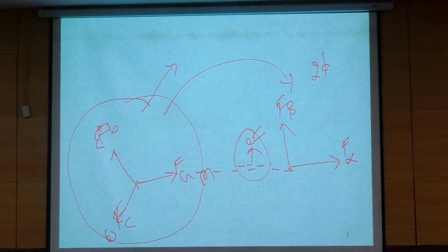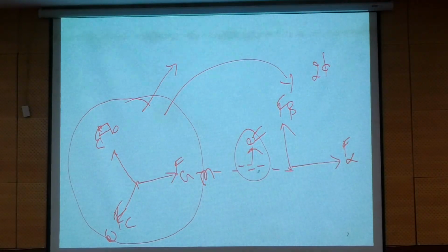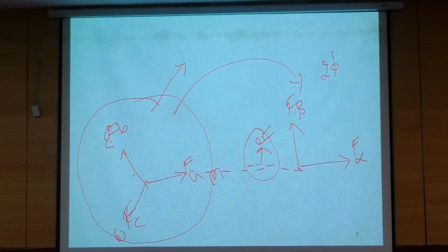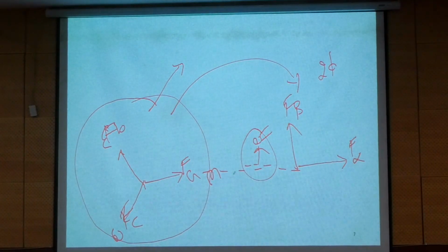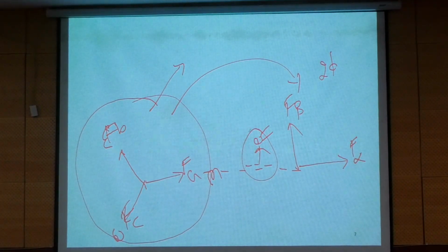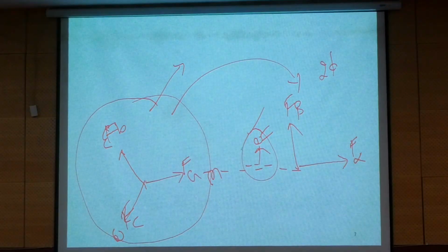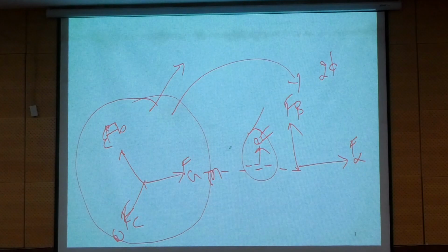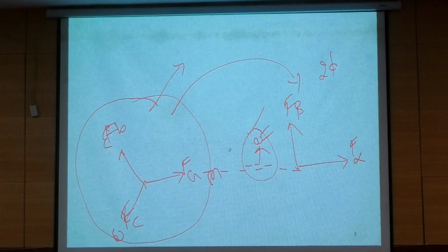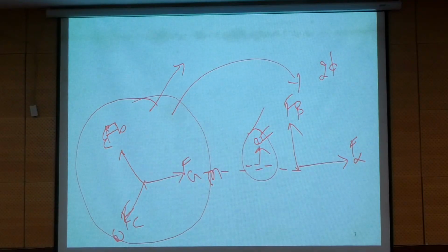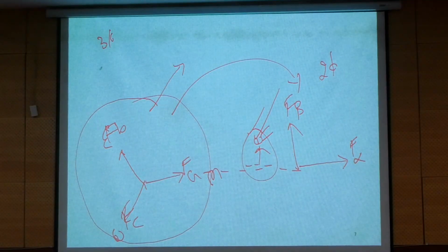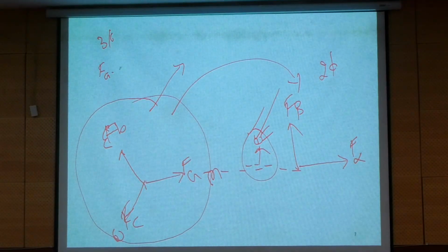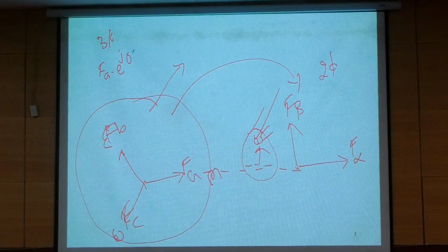Now, how can we express the net MMF produced by three-phase with respect to this reference phasor, the common phasor between three-phase and two-phase? You need to take care of the space displacement angle between the reference phasor and the individual vectors. So in three-phase, the net MMF is FA into e power j0. Why e power j0?